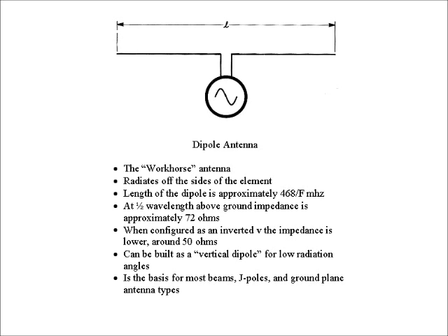So you can almost look at an antenna and know what band of frequency it's typically for. Pretty easy, pretty straightforward, and pretty accurate. Another interesting thing about antennas: if an antenna is exactly a half wavelength above ground, the input impedance is going to be about 72 ohms.